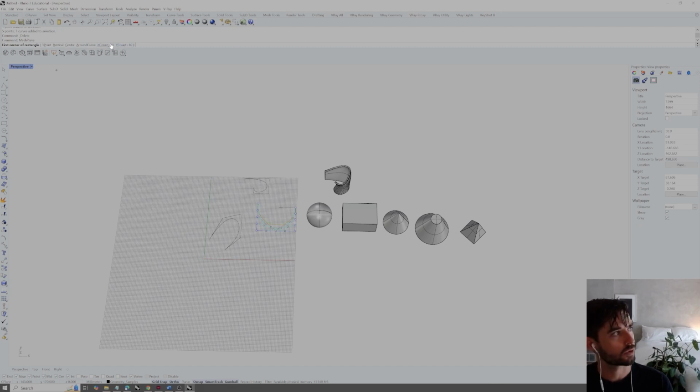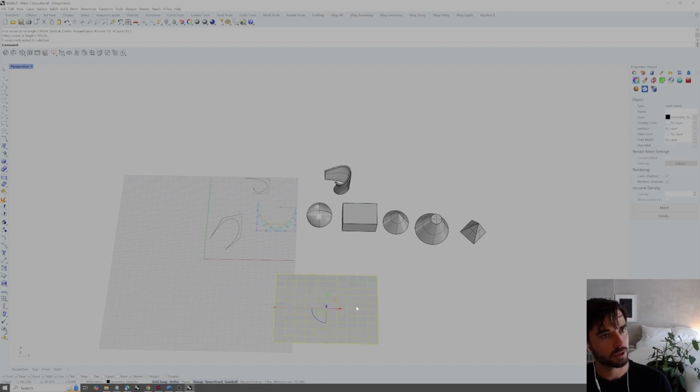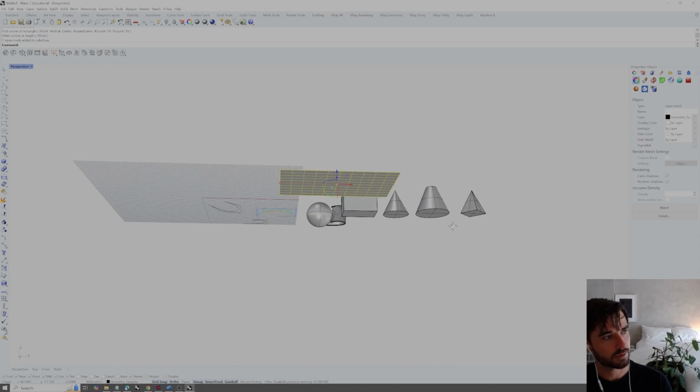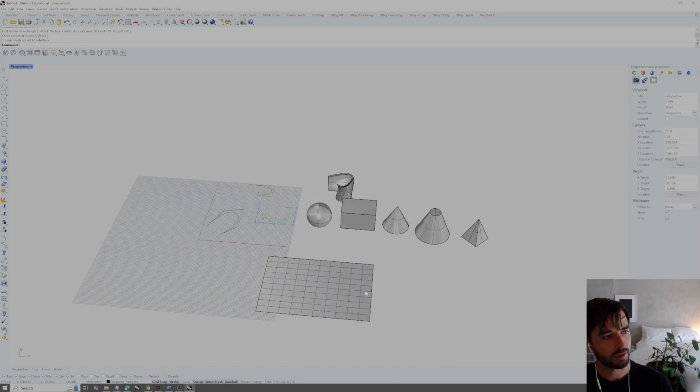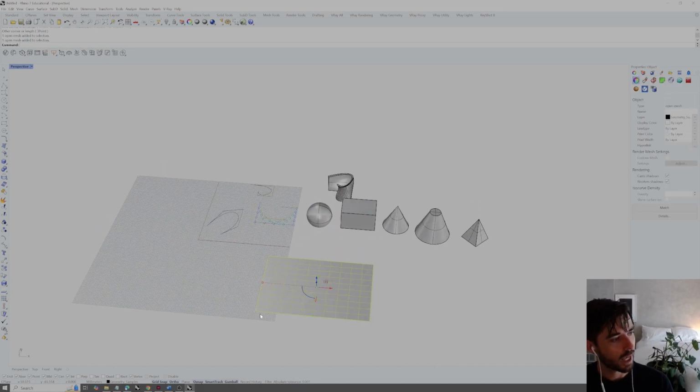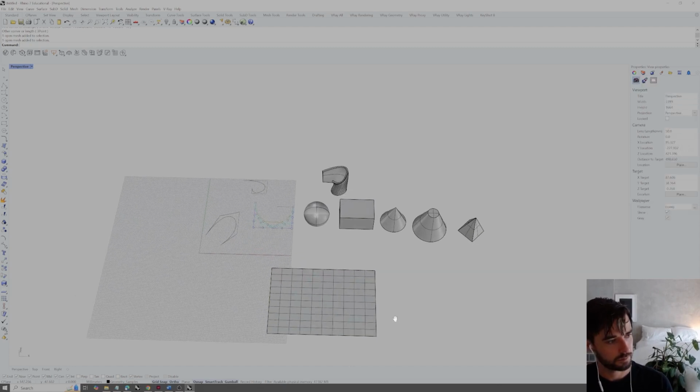This is part of that discrete parameter, meaning there's only so many units or only so many vertices in the X-axis and Y-axis. So if we leave those both at 10, when we click those 2 points to define that mesh, we see it's an open mesh, meaning it's flat, has a front and back face, but no thickness, and it has 10 units in each axis. So 10, 1, 2, 3, 4, 5, 6, 7, 8, 9, 10 faces in both axes.